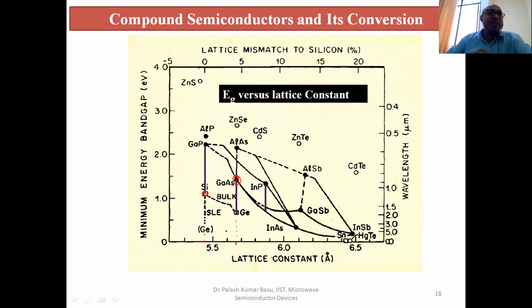Why? Because this lattice mismatch creates a lot of defects. And what is the amount of defects? You can see 5.6 minus 4.8, divided by 4.8, times 100. That's the amount of lattice mismatch there is.